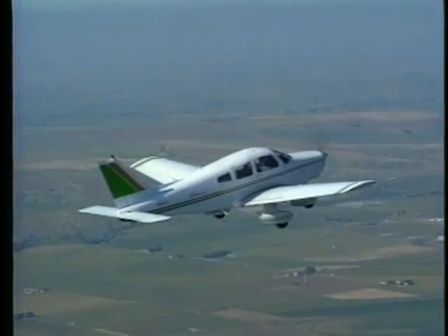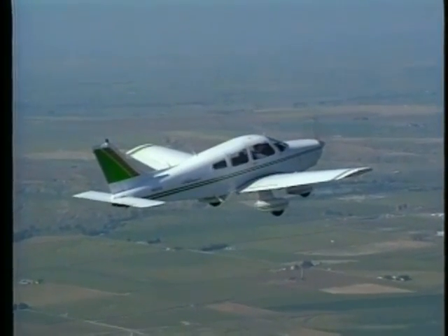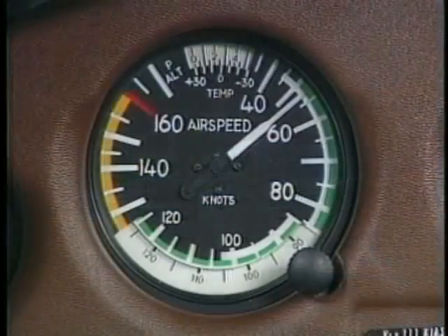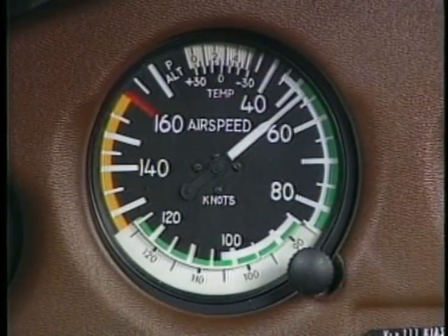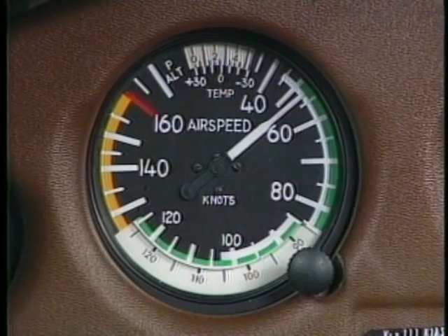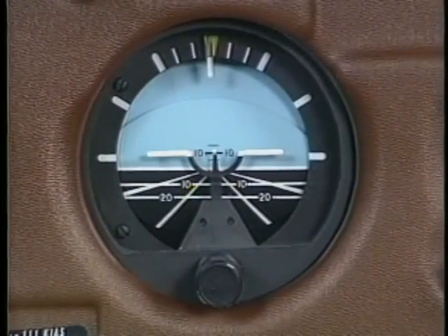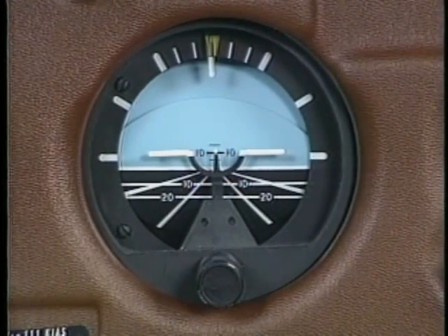When you roll out on the recovery heading, the airspeed should indicate just above stall speed. With practice, you'll learn to coordinate your rollout at a precise airspeed. Since full power is used throughout the maneuver, your airspeed is controlled by adjusting your pitch, which is the key to properly executing the chandelle.